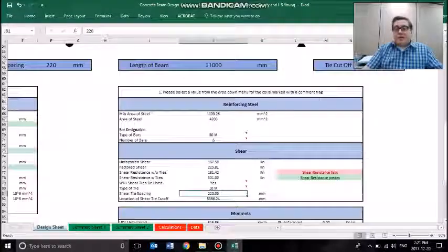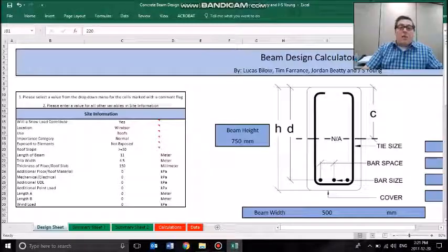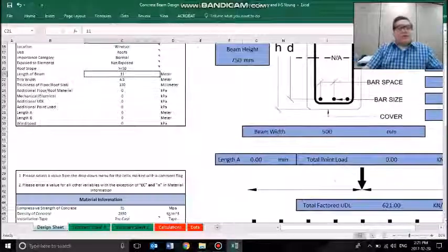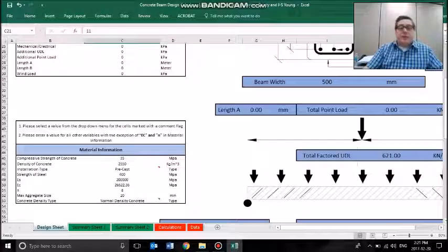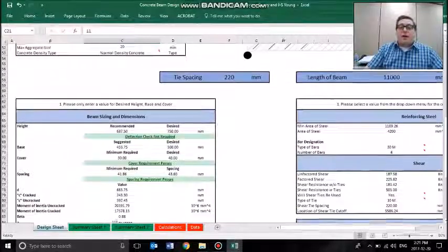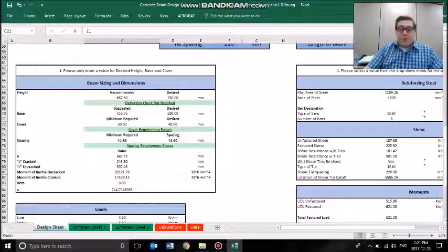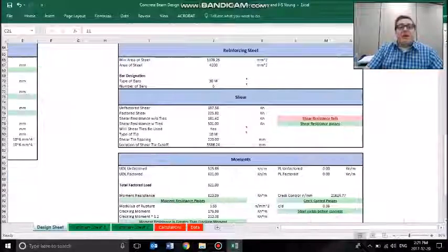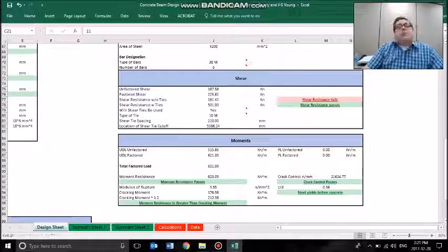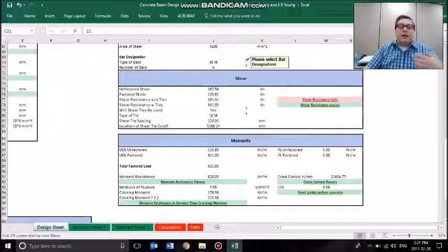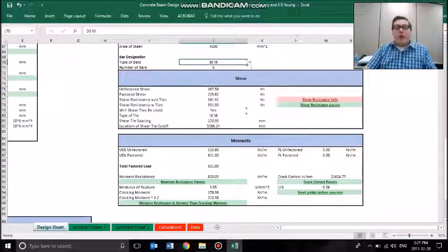So as we can see, we've gone through the whole thing, inputting what we'd like from the test. When we're looking at a test example like this, we can see the way we've set it up with 630 M bars. We can see it totally passes in this circumstance. So we can see that our sheet is able to be designed for any sort of environmental circumstance, any location, and allows you the ability to select bars and number of bars to build a more economical option instead of just providing a default.